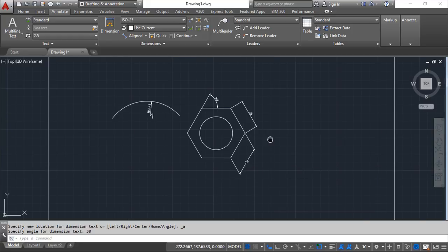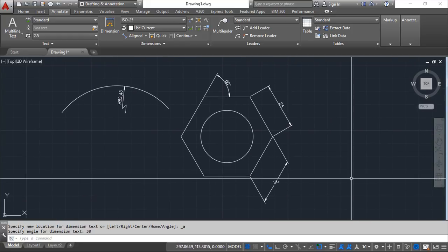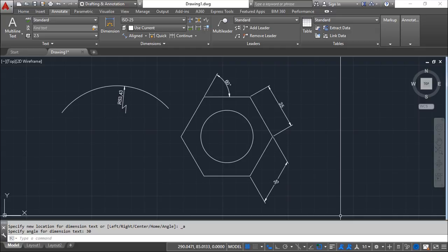Okay, so this is another possibility to use with linear dimensions or aligned dimensions, to turn them oblique on the angle you give. I use this example for these isometric possibilities, but you can use other kinds of angles, because you may have specific situations where you want to have your dimension aligned with another particular and specific case.